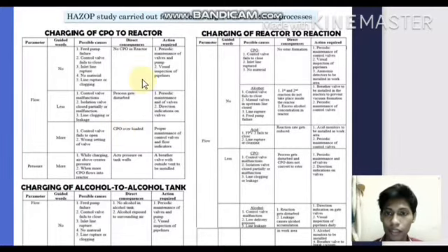Basically, the action required is needed to avoid the possible causes, such as doing maintenance on pump or valve, and visual inspection of pipelines to avoid line rupture or clogging, and feed pump failure and so on.